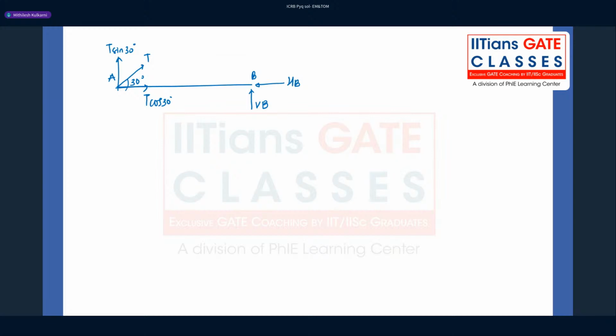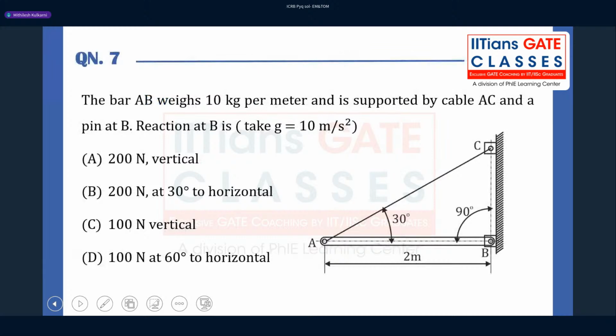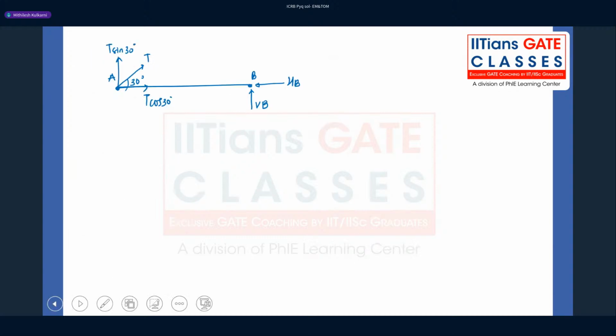Then we know that the bar is having certain weight, that is 10 kg per meter. So the distance is 2 meter, so if we assume g as 10, which they have mentioned, it will be 100 Newton per meter, and it is a 2 meter bar, so we can say 200 Newton of weight, and that CG will be at the center since it is uniform.